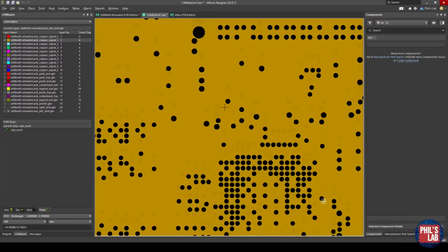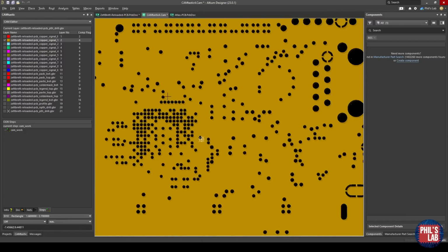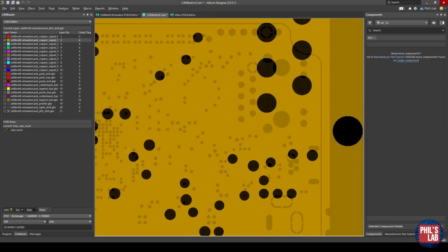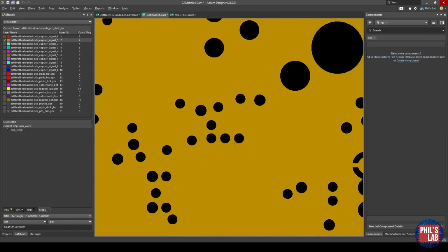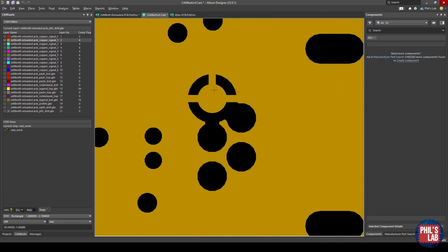So in that way, I would select individual layers. For example, my ground copper boards, this is what I always really encourage as well, to make sure I don't have too large ground or reference plane cutouts. For example, that I always have slivers between my via drill holes and so on, and that I don't have too many of these large cutouts.